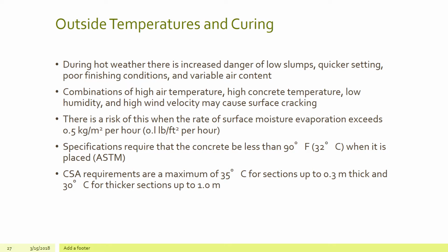There's a risk of this when the rate of surface moisture evaporation exceeds 0.1 pounds per square foot per hour. Specifications require that concrete be less than 32 degrees Celsius or 90 degrees Fahrenheit when it is placed. CSA requirements are a maximum of 35 degrees Celsius for sections up to 0.3 meters thick and 30 degrees Celsius for thicker sections up to a meter thick.